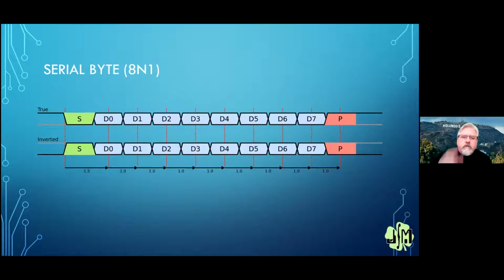But anyway, again, serial is very simple. We're going to have a start bit. We're going to send our data bits in order from LSB to MSB. Remember, if we are using parity, this bit, which I'm calling D7 here, is going to be our parity bit, and then we'll have one or more stop bits. And there we go. Now this is the signaling, I guess. The transmission medium could be wire, could be radio, could be infrared, it doesn't matter. This is how we're sending the bits.